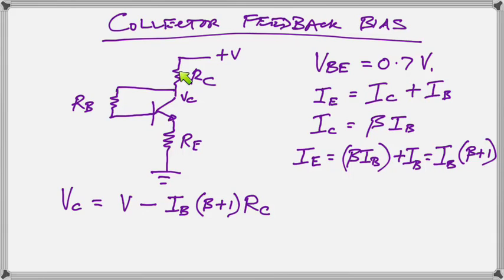So from a voltage point of view, we have beta plus 1 IB here, and we have beta plus 1 IB here, and then it splits, and beta IB goes through the transistor, and 1 IB goes through that there. So by moving the split from up here to up here, we've slightly increased the current flowing through here, so basically, we have identical current now flowing through RC as through RE. So that is the change in that circuit.